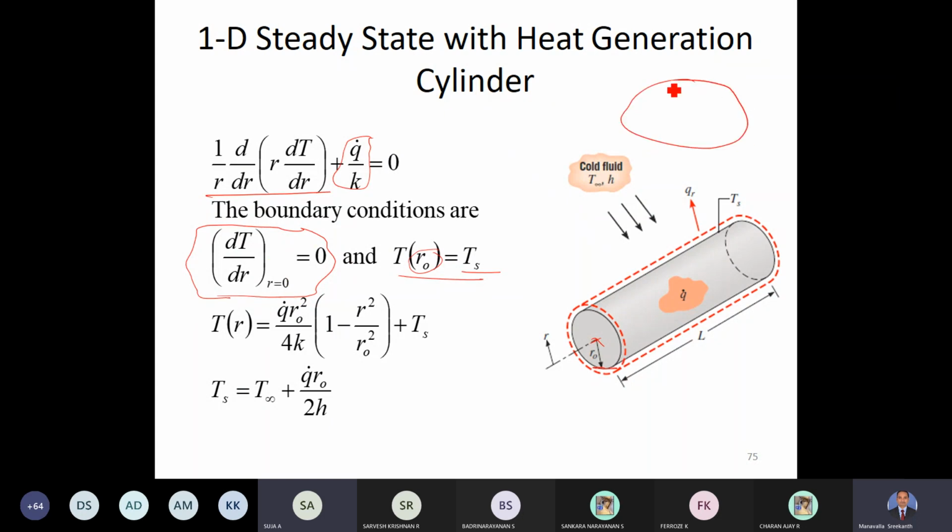You see here, this is the cross section of a cylinder, and at the center, things are symmetrical. Whatever is happening on this side will also happen on this side. So things are very much symmetrical. In fact, by taking advantage of symmetrical conditions in computational fluid dynamics, instead of making computations all over this surface, we take only one region. We compute only in one region and apply the symmetric boundary condition on this wall and on this wall. So basically, at the center point the condition is dT/dr = 0. Why? Because of symmetry, and symmetry means insulated condition, adiabatic condition, therefore no heat transfer, therefore no thermal gradient at that point.